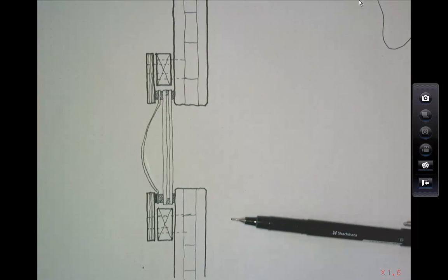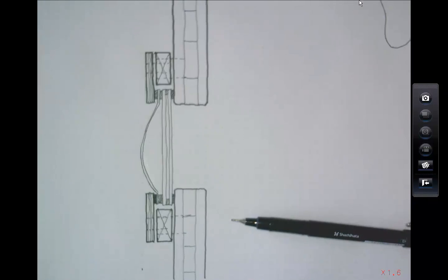An untreated piece of cross-laminated timber would allow flame to spread across its surface. So once you put one of these clear coatings on, it will stop it doing that. And you can get some quite eco coatings now, which don't smell, and they haven't got a whole load of nasty chemicals in them.